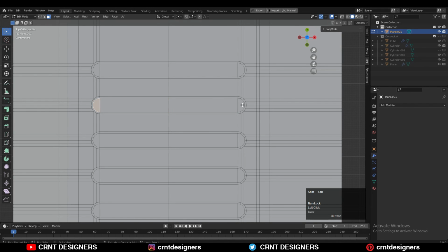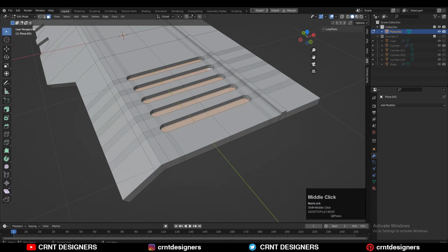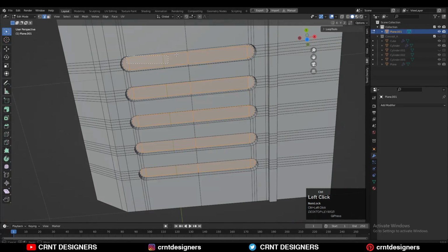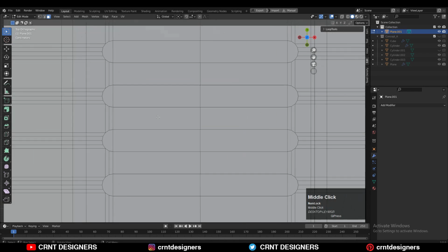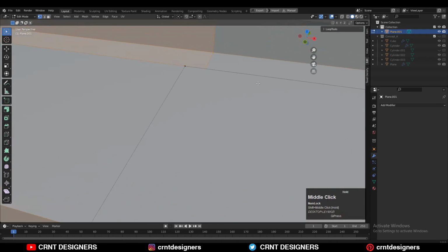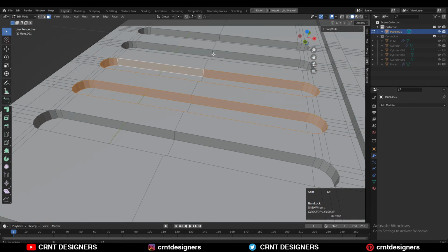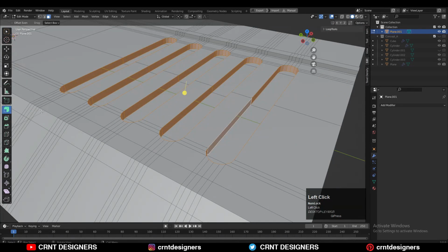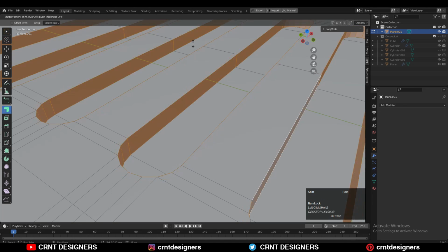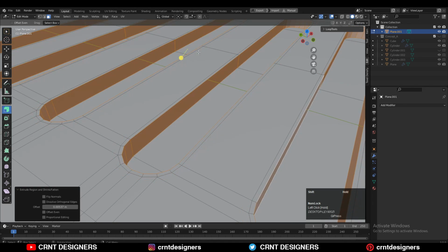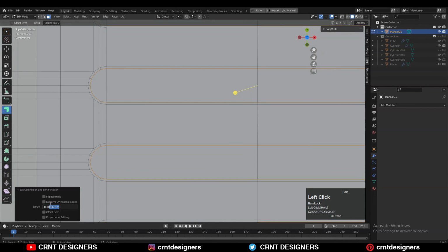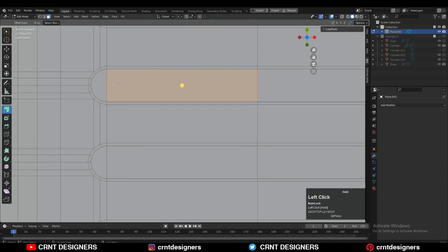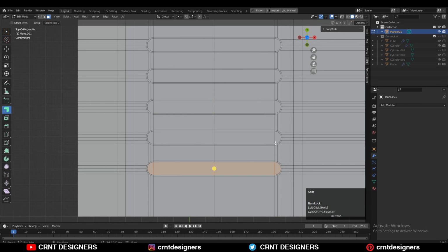Then I need to select these faces like this with the shift select. And then just deselect the faces, only the edge loop will be there, and then dissolve these edge loops, meaning that insert operation which we created the first time. And now I have selected these face loops and then used the extrude along the normal to create the outer loop structure around that boolean, so it will support that boolean. That's also important, and I forgot that the first time.